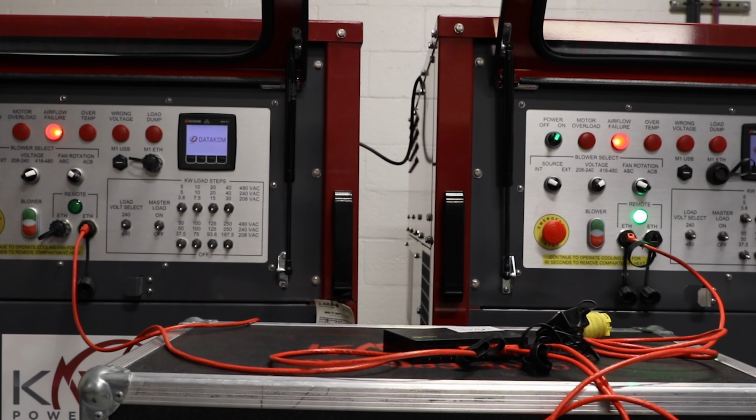We can verify this by highlighting the group and then clicking Group Settings. Notice we have 1500 kW in the max kW field, and our estimated fan power draw in the offset kW field. You are all set to begin writing your script, so you can click OK to close out that window. To begin writing your script, you first need to click on the Scripts tab on the left side. In this window, you will both write and execute your scripts.